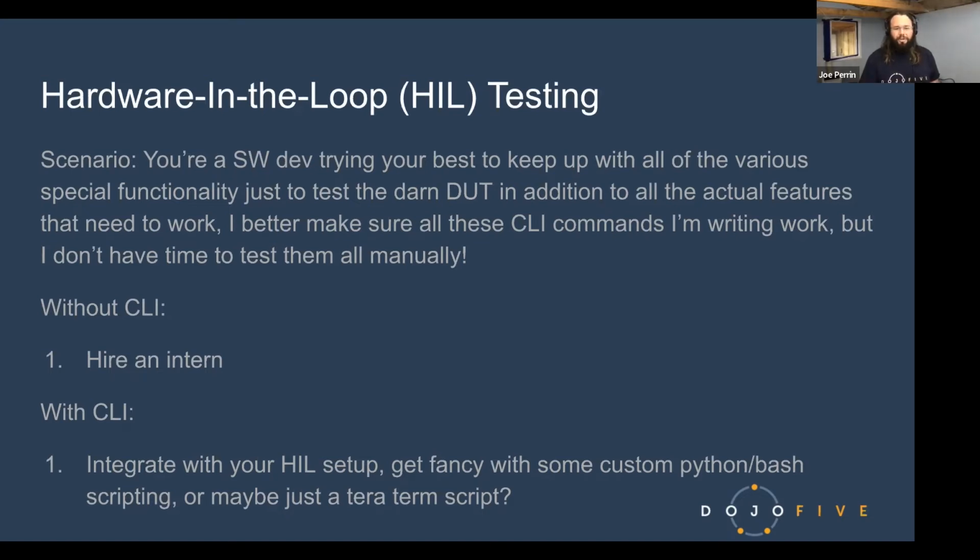Maybe you can automate that, but why go through that trouble when you've already implemented a CLI and now you just need to have PyTest or something sending commands over UART and seeing that it does the correct thing in response. So you've already instrumented your whole system by implementing the CLI to give all these tests for all the other groups in the company. And now we can use it for HIL too.